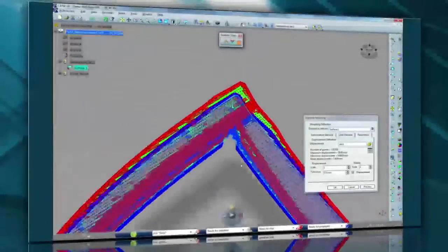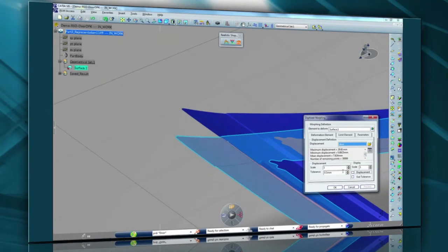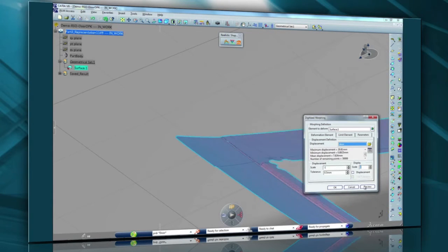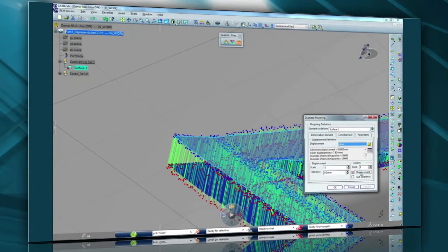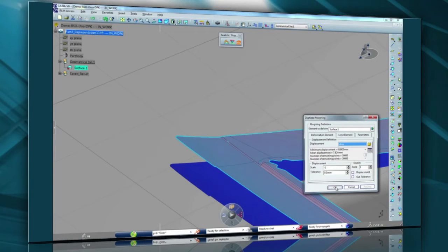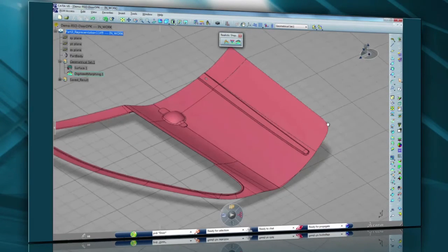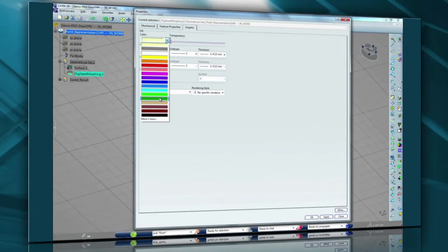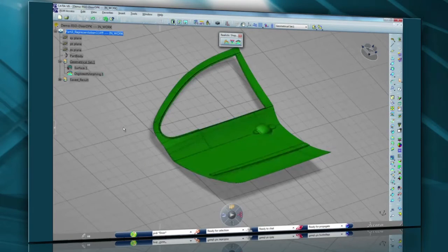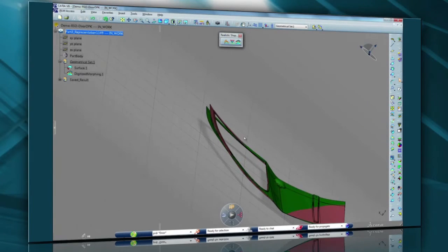As we want to create the tooling compensation surface, we apply a scale of -1 to counter-deform the tool, which is necessary to ensure the correct part. We can display a preview, so you can see here in blue the difference between the original and the compensated geometry. And again, we apply a scaling of -1 and recompute for a completely new surface, in red. This is the compensated tooling surface. This is a very effective and fast process. We have many customers today using this in production, not only for sheet metal, but also for plastic parts, composite parts, forging parts, and many other processes.